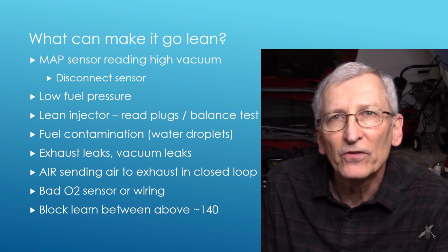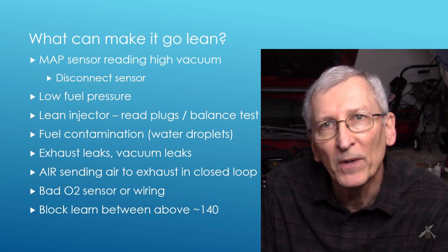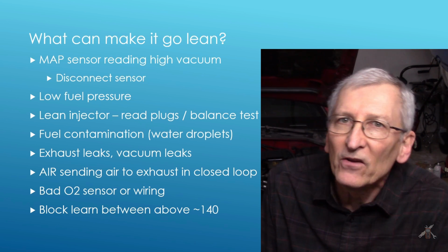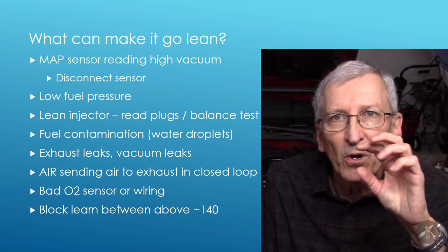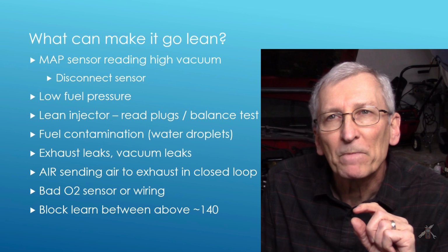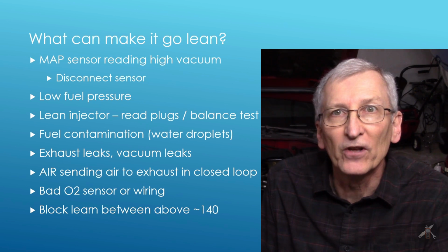Fuel contamination. The service manual cautions that if you have water in your fuel, even small amounts that get picked up, you know, it gets fed in along with the fuel, and your engine will burn it if it's small amounts. But it will come across with making the oxygen sensor see a lean mixture.